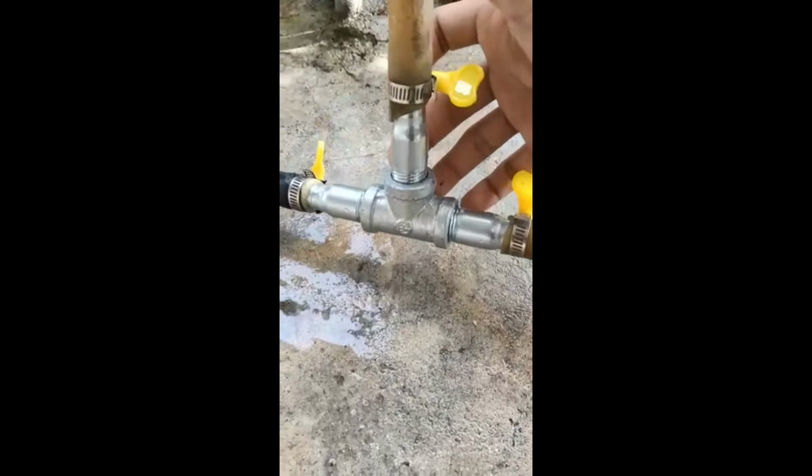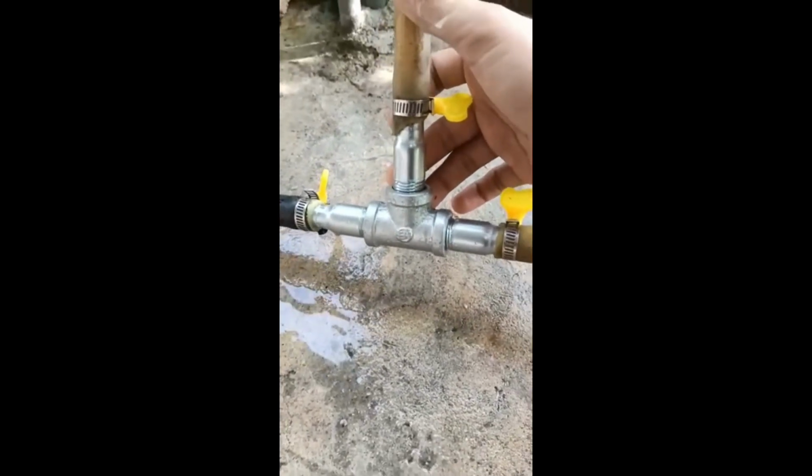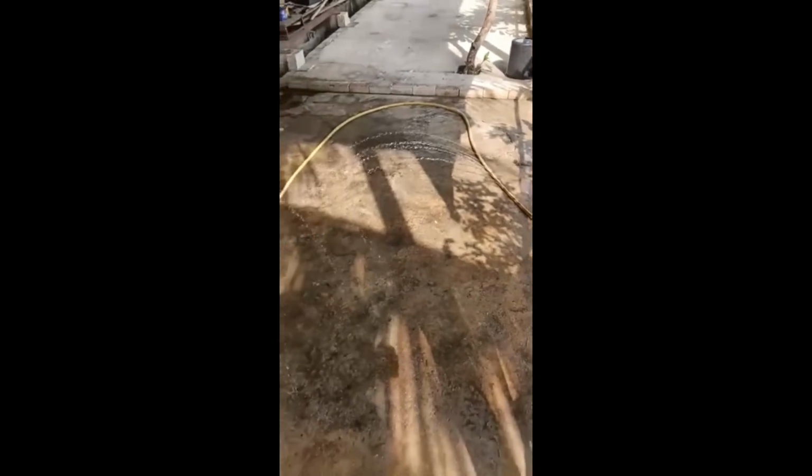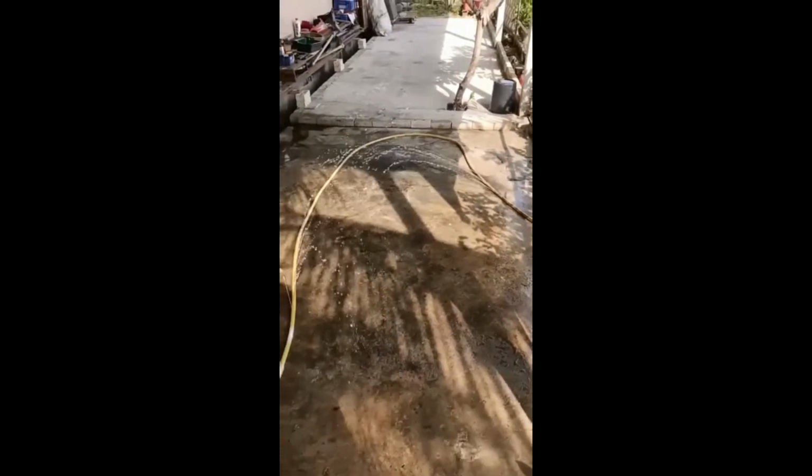For second configuration, we will use T connector to make it closed loop, and also use hose clip to make sure no leaking. After that, make 5 holes at equal distance, that is 10 cm, and another 5 holes at here. Finally, open the tap to maximum and measure the flow rate of the water.